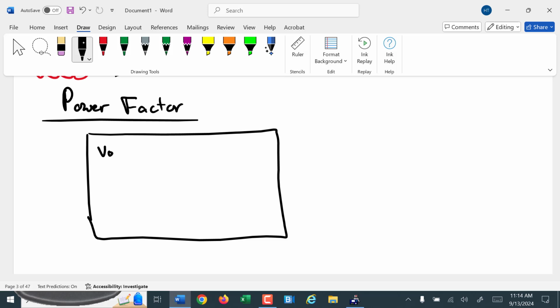Usually there's the voltage, there's the current. If you have a low-high motor, there'll be 2 currents listed there. And there's going to be a horsepower rating. If you look really closely, you usually find that those numbers do not necessarily match up.